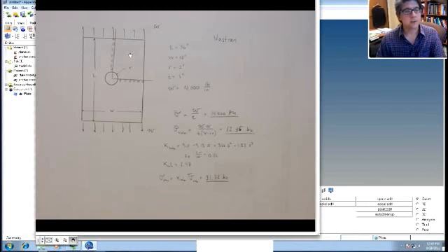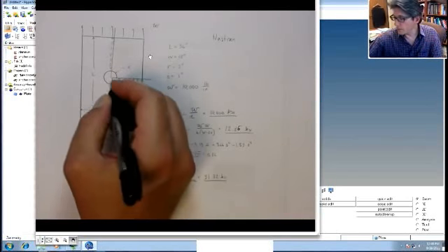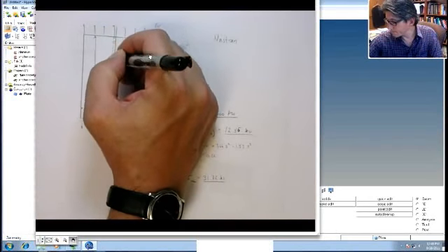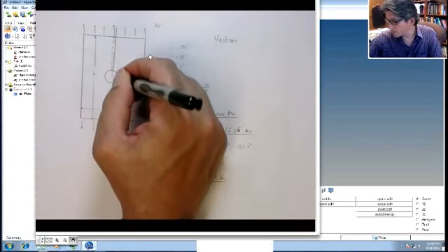Sometimes it's actually easier just to create the geometry because you don't have to do the cleanup like you do when you import in CAD geometry. And that's a whole other topic that I won't go into, but we'll make the geometry. So when it's a planar geometry, all that you really need to do is define the bounding curves for the geometry.